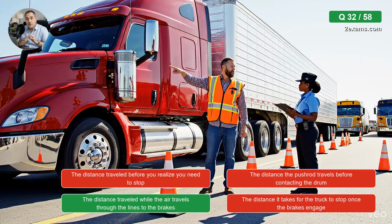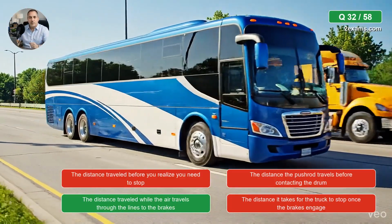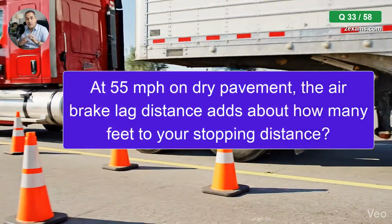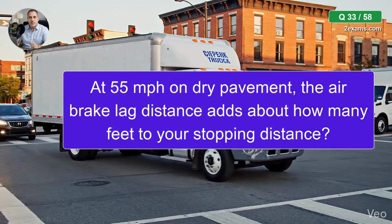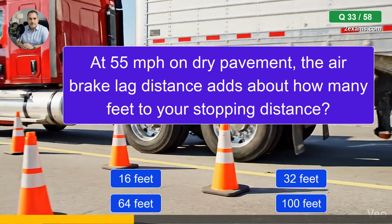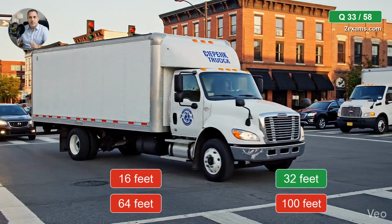The correct answer is the distance traveled while the air travels through the lines to the brakes. At 55 miles per hour on dry pavement, the air brake lag distance adds about how many feet to your stopping distance? The correct answer is 32 feet.